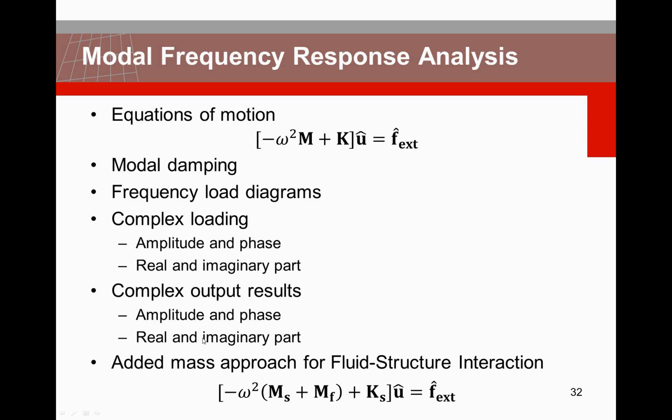In case of the fluid structure interaction, if you want to do modal frequency response analysis, you are limited only to an added mass approach. You cannot do added damping because that doesn't fit in the eigenmode calculation.